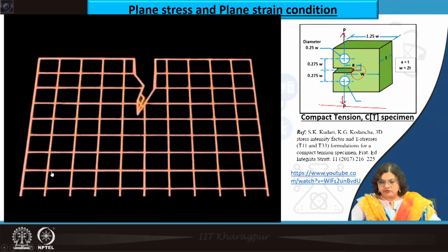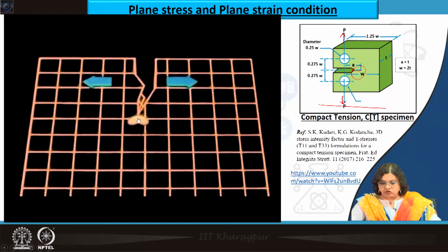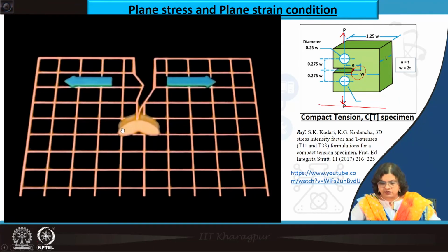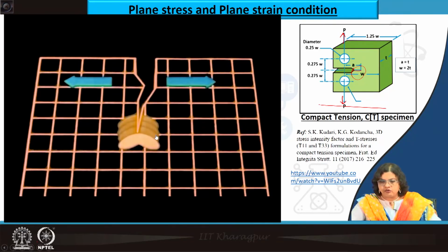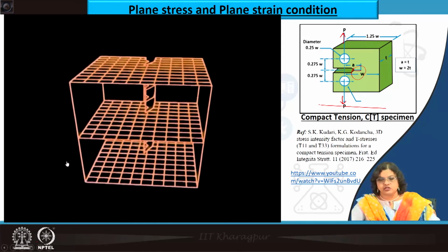Essentially, when we are having the stress along this direction, the crack grows in the perpendicular direction and it forms a plastic zone size which eventually grows as we are applying higher and higher stress values. And when it grows, it actually leaves a wake of plastic zone on the crack side, and that is dependent on the plane strain fracture toughness of a material.